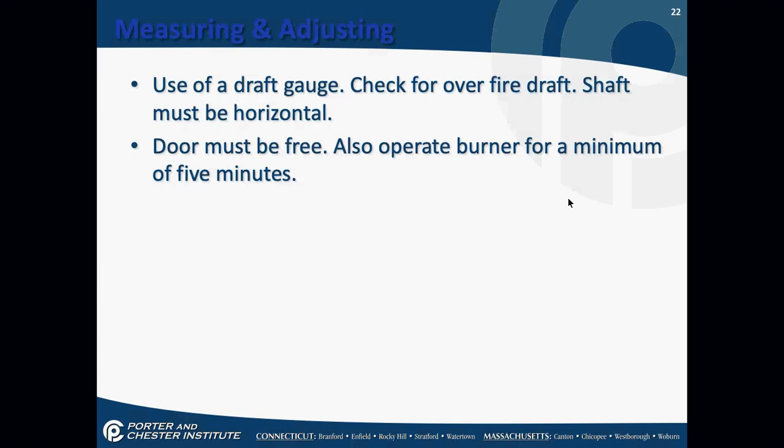Let it warm up. What part of it am I trying to warm up? The flue pipe? Combustion chamber? Both are actually good answers, but the end thing I want to warm up is the flue and the chimney. Before the chimney is warm, we're not in our normal operating position. We need to be at normal operating standards before we do much of anything.